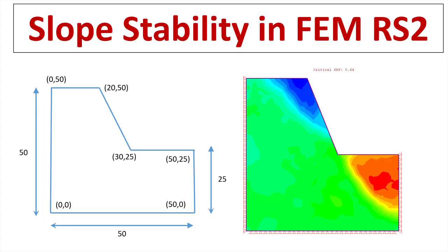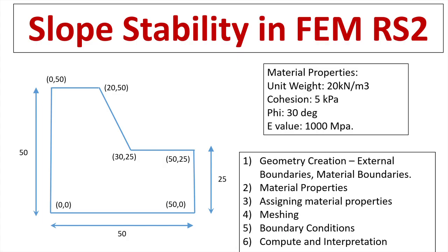That is, factor of safety is obtained by dividing resisting force by driving force. Whereas strength reduction factor means by how much factor we reduce the material strength, the failure starts. Suppose in a problem SRF comes to 1.5, that means if the material strength is reduced by 1.5 times, then only failure happens. As explained, we are solving the same geometry and same material properties.